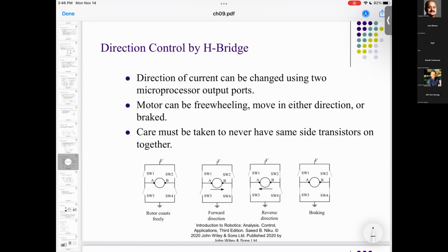So you can change the speed. Reduce the speed, torque will increase; increase the speed, torque will decrease. And again, you can have gear ratios depending upon the type of gear train that you use. The equations for the gear ratios are different.